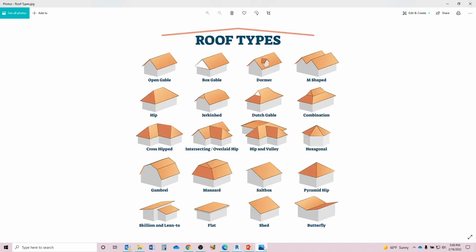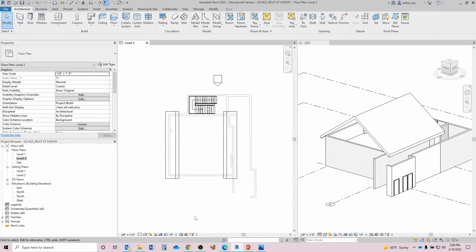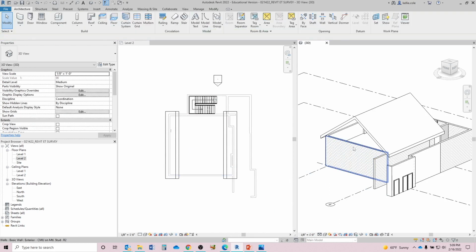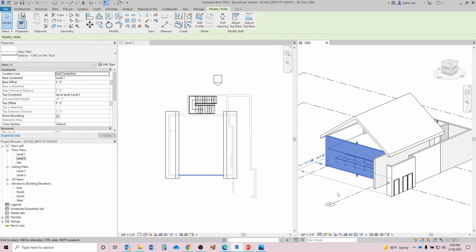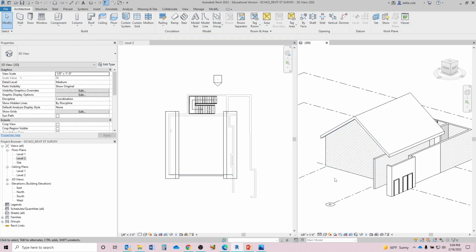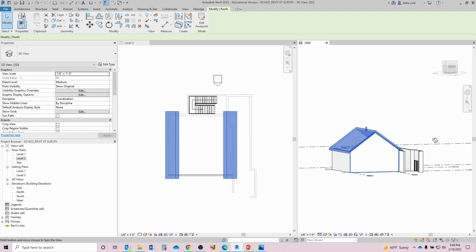Now what are all these roofs and their names? Today we're simply going to focus on 2. The left 2 on the screen, an open gable, and that hipped roof. Let's do one more thing with roof. Let's attach the wall to the roof at the open gable. Revit makes this very easy for us. I don't need to wall edit. I will touch the wall that I want to connect to my roof, look in the middle of my ribbon, select Attach Top Base, then click the roof. Okay. Then I have a gabled wall.